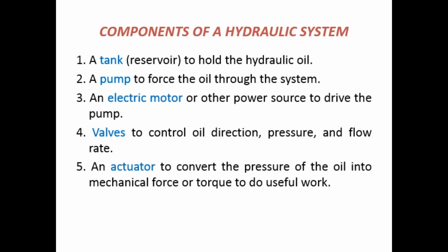Now if the oil is present in the tank, how do we transport the oil from the tank to various components? For that purpose we require a pump. The next important component is a pump to force the oil through the system, or to take the oil from the tank and supply it to other components of the system. Now if the pump has to work, it has to be connected to a motor. So the next important component is an electric motor or other power source to drive the pump. Basically we go for an electric motor that will be coupled to the pump for the pump to run.